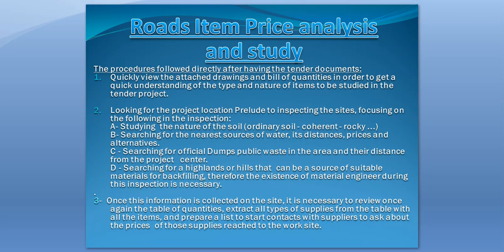First of all, studying the soil, whether it is ordinary, cohesive, or rocky, and searching for the nearest source of water and its price, its distance, and alternatives, searching for the public waste dump in the area and its distance from the project center, and searching for highlands or hills that can be a source of suitable material for backfilling. Therefore, the presence of the material engineer during the inspection is necessary.